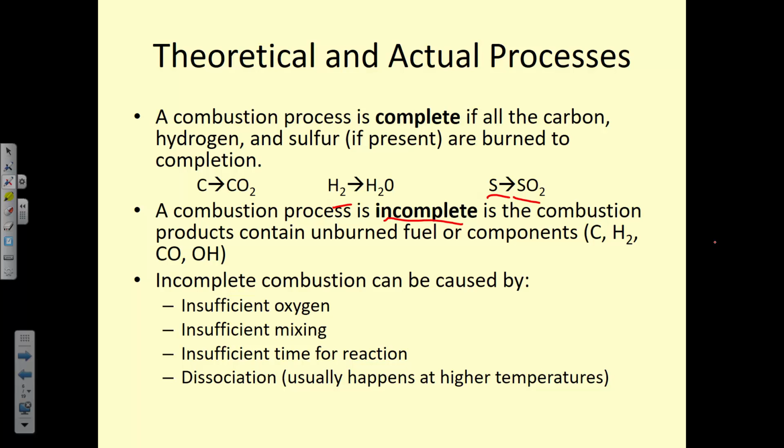So it's an incomplete process if we have any free carbon, hydrogen, carbon monoxide, or OH molecules at the end of the combustion process. Anything other than that, if we just simply have carbon dioxide, water, and sulfur dioxide, we consider it to be complete.